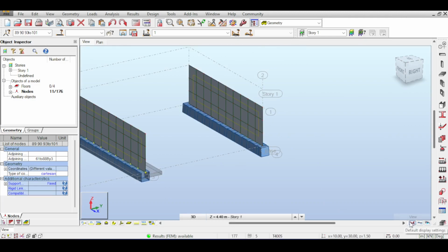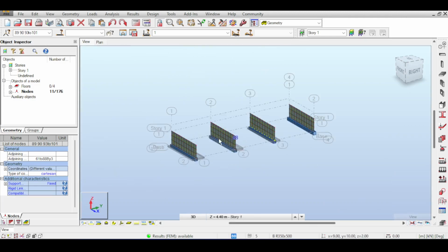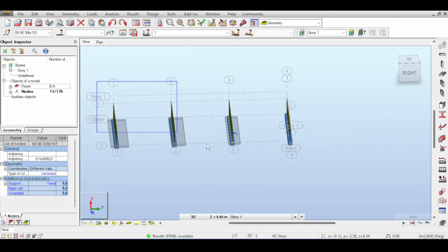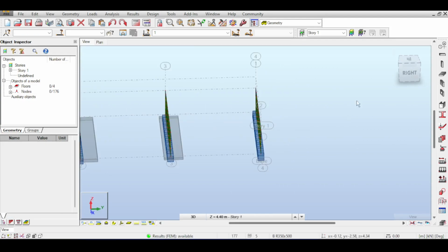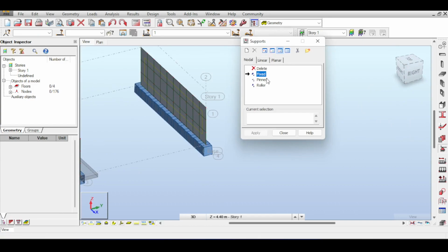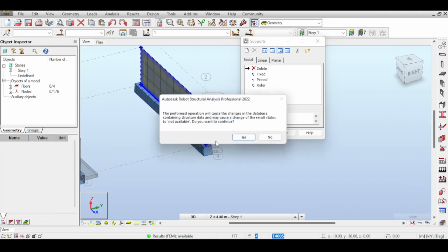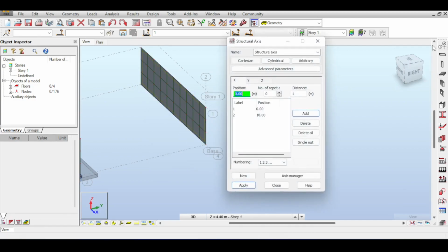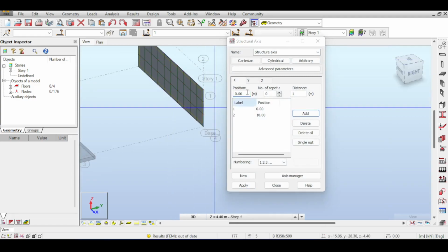Now, what I'm going to do is going to be a nightmare, by the way, and it's actually much easier to use those techniques that we have discussed just now rather than using my detailed modeling. But I just wanted to discuss this with you just to show you. So, first of all, I will remove the fixed support. There is no support at all now, because I will be drawing the foundation myself. So I'll now draw a foundation, and of course I need the positions here.